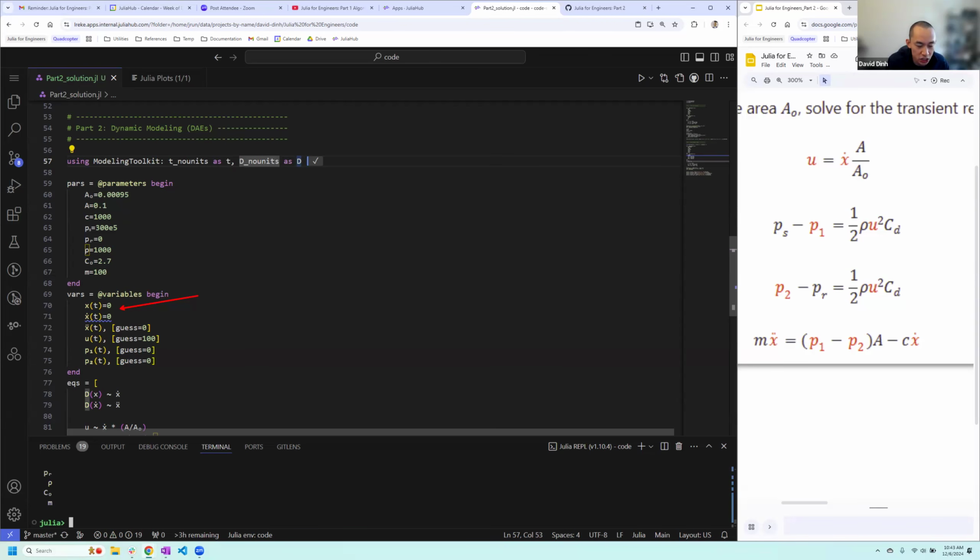You can think of the action in the very beginning, the actuator is just in its upright position and is not moving at all. And then all of a sudden, something happens, it fails, and it moves quickly. That's what we're specifying here. Initially, there's no movement, and it's at its topmost position. In order to give guesses to the solver to help it out, like we did before, we simply specify it with the guess keyword right here.